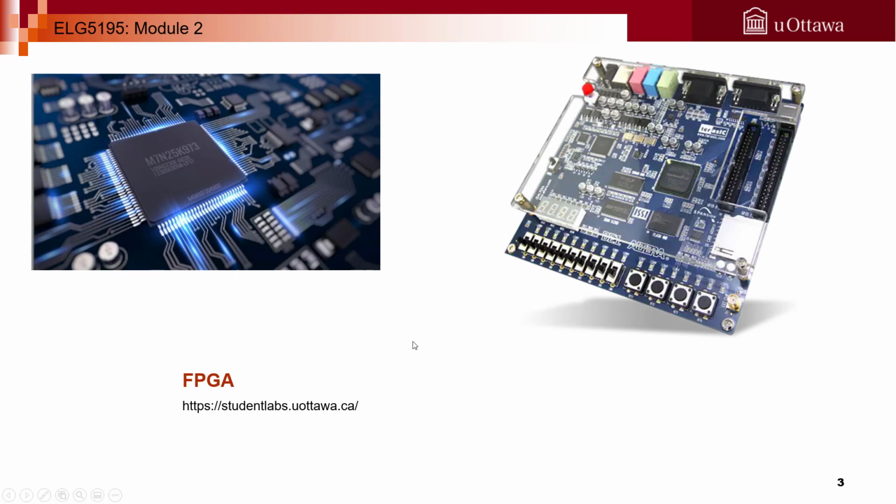When it comes to the FPGA, the University of Ottawa has the Cyclone FPGA, and it's found at the CBY lab on the 3rd floor. In this video, I'm going to ask you to implement a multiplier, a parallel multiplier, using the one-hot assignment method. You remember the one-hot? The one-hot employs one flip-flop for each state. Exactly, one flip-flop for each state.